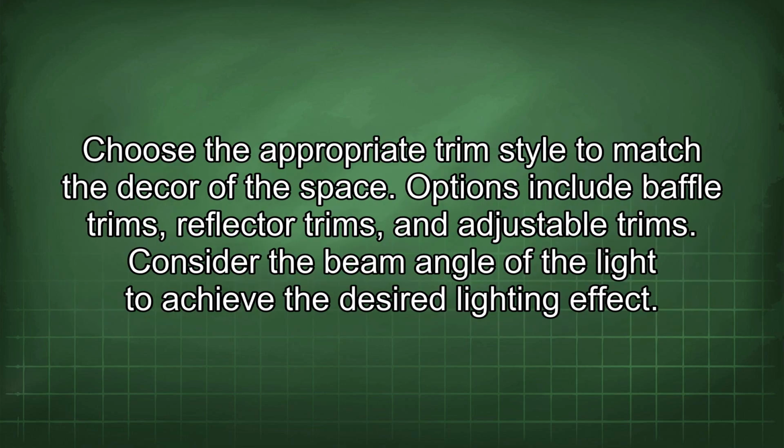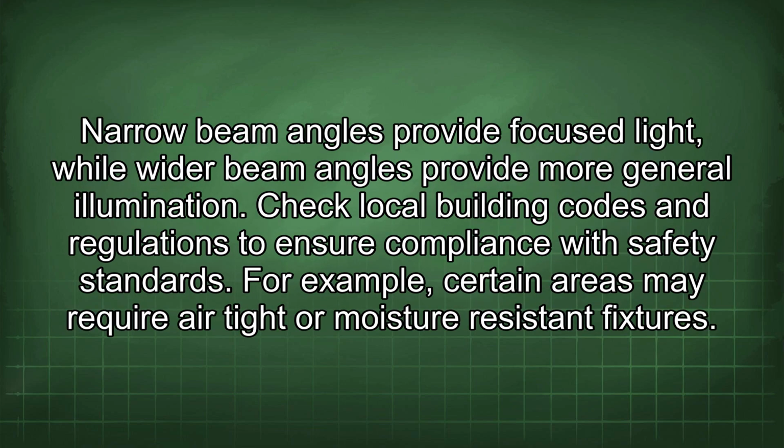Choose the appropriate trim style to match the decor of the space. Options include baffle trims, reflector trims, and adjustable trims. Consider the beam angle of the light to achieve the desired lighting effect. Narrow beam angles provide focused light, while wider beam angles provide more general illumination.